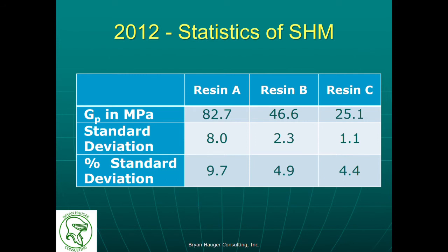For the statistics of strain hardening modulus, we look to a presentation from Plastic Pipes 16 in 2012 by authors from Kiwa Technology. The conditions used in this study were identical to the ISO 18488 test method and include a round-robin study conducted on PE80, PE100, and PE100RC, or a highly stress crack resistant material. In this study, 8 laboratories conducted testing on those 3 materials, with replicate measurements varying in number from 3 to 9, depending on test lab.